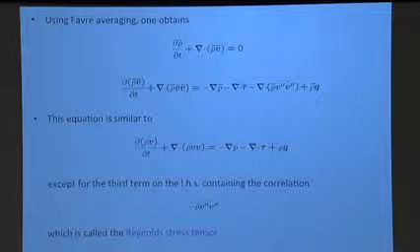How do I know it's a transport term? Because it's a divergence. Okay? Divergence of something, that's always transport term. Because if you integrate over this, integrate over divergence, that gives you just the fluxes over the walls. Okay? So that shows integrating this over space. That shows that this is a term that just moves stuff from here to there. Okay.